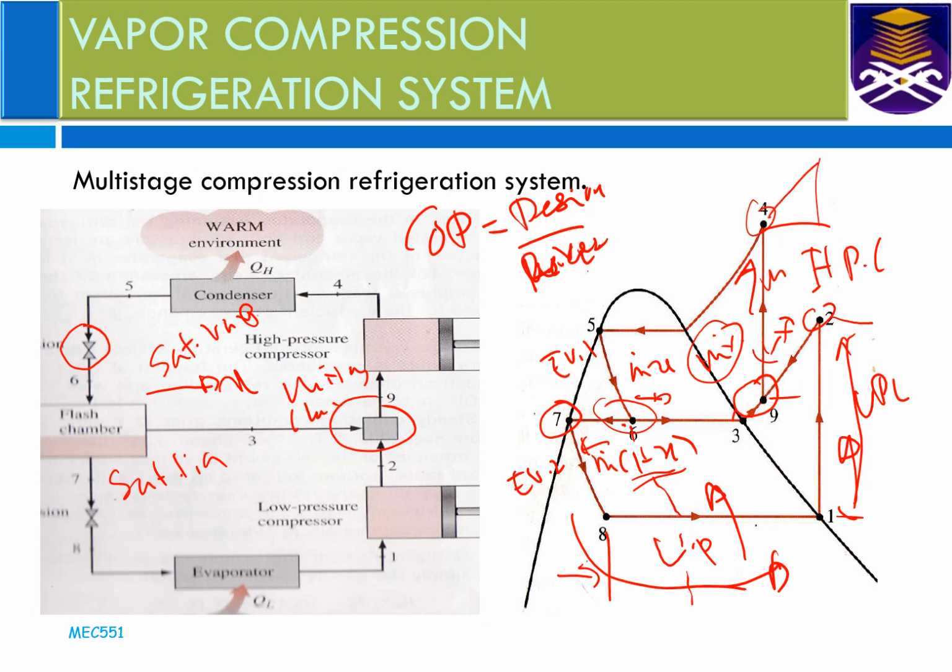If it goes directly from 1 to 4, the required power input to the compressor is large, but with this arrangement it will decrease the required power input for the compressor a little bit. However, the amount of heat rejected is lessened, so it is not suitable for the heat pump process.